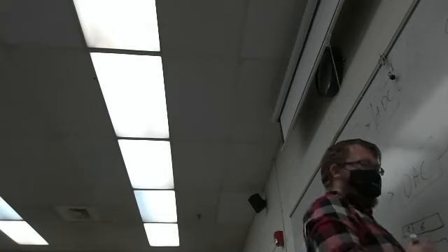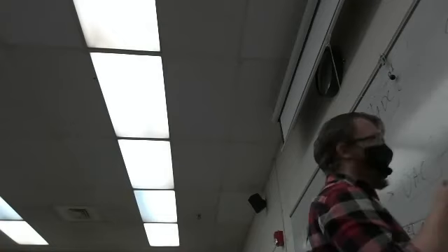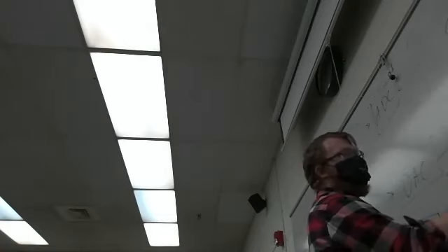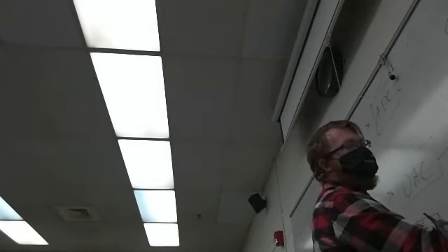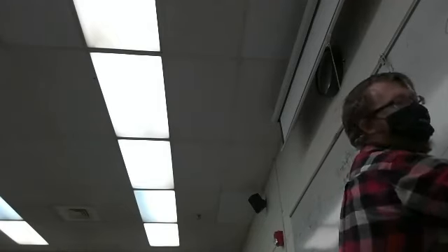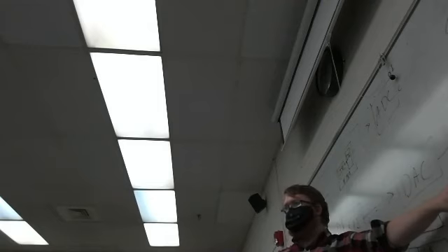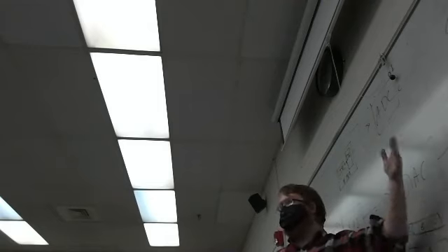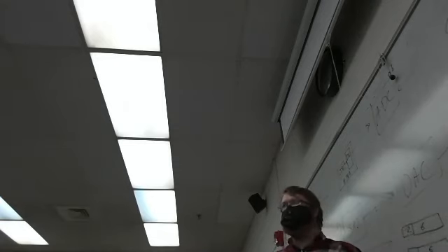A lot of times the real filter will look more like, it'll have ripple, and then it'll have a peak, and then it'll plummet, and then it'll have ripple. Or Butterworth. Well, the advantage of the Butterworth is to not have that ripple. Oh, cool. Is to be linear. Yeah, but it doesn't have those good properties, so you'll need to make your design decisions. And a lot of times what you'll do is you'll actually generate the filter in Python or something, and then just load that into memory and use that for the convolution.